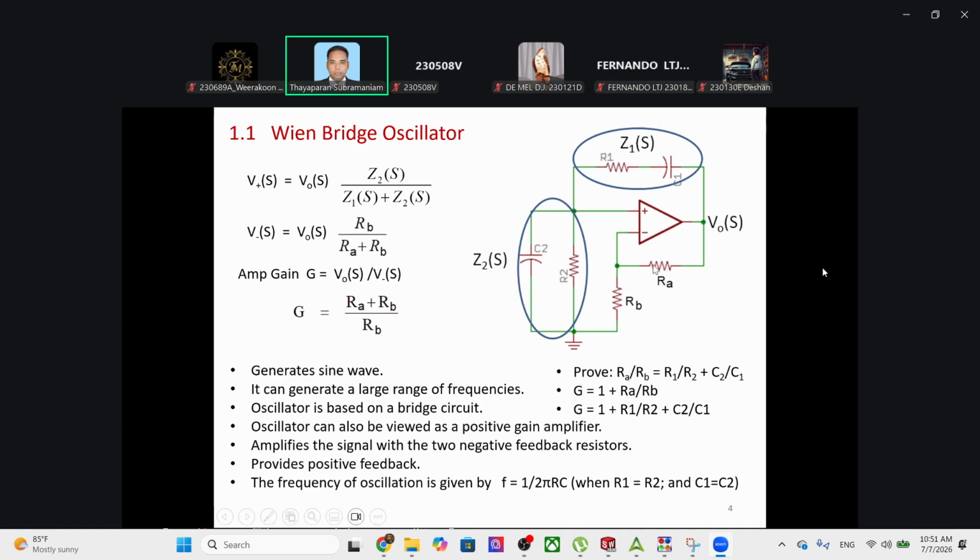If the amplifier is not working properly, we have only 3 components here: the amplifier, RA, RB. You have already measured RA, RB. So if it is not working properly, obviously the problem is with the op-amp. Then you can either change the op-amp or request a new one. That is the approach of designing analog circuits. You will enjoy it if you do it in the right way, in manageable steps. Measure the capacitance value also, whether it is within that range.